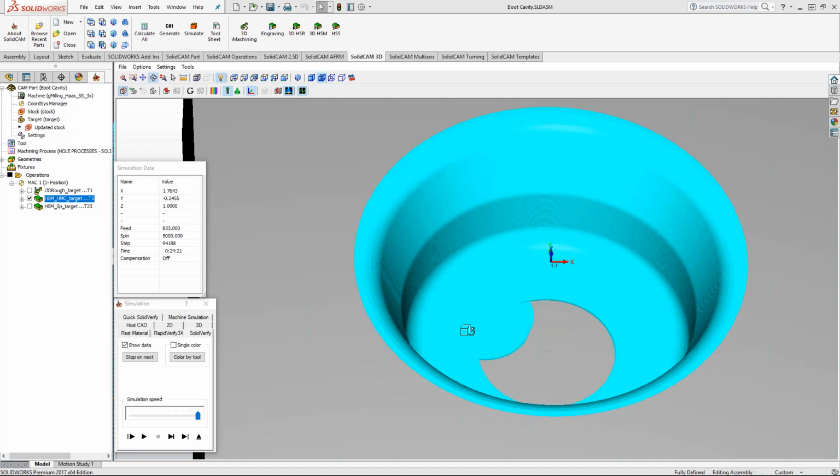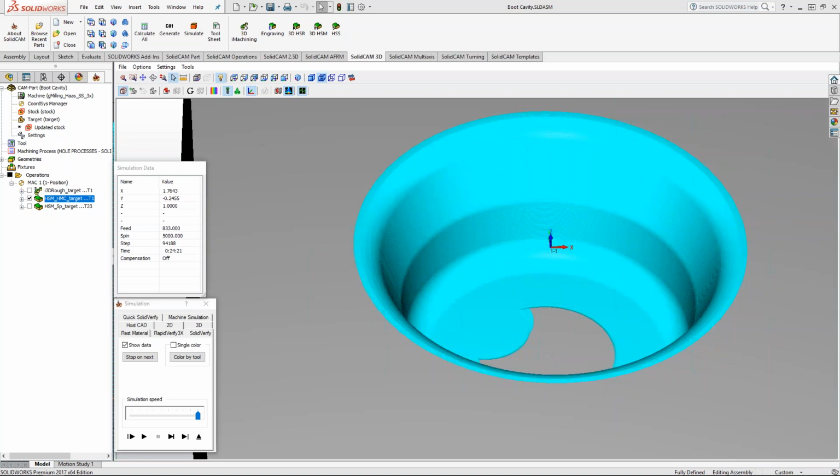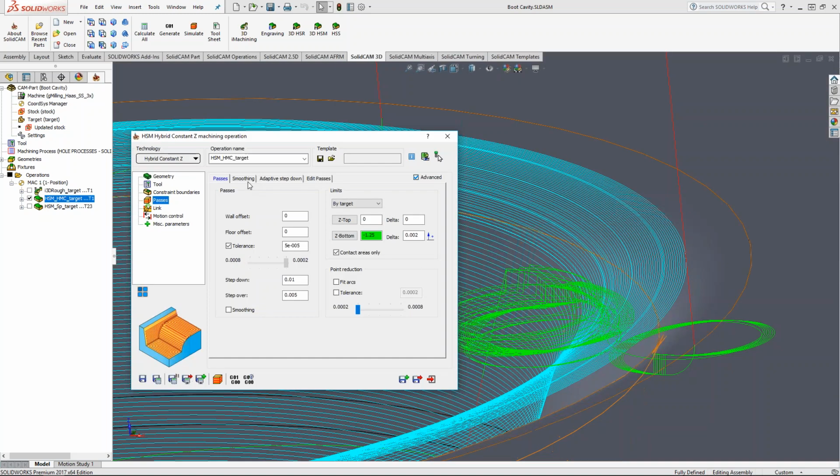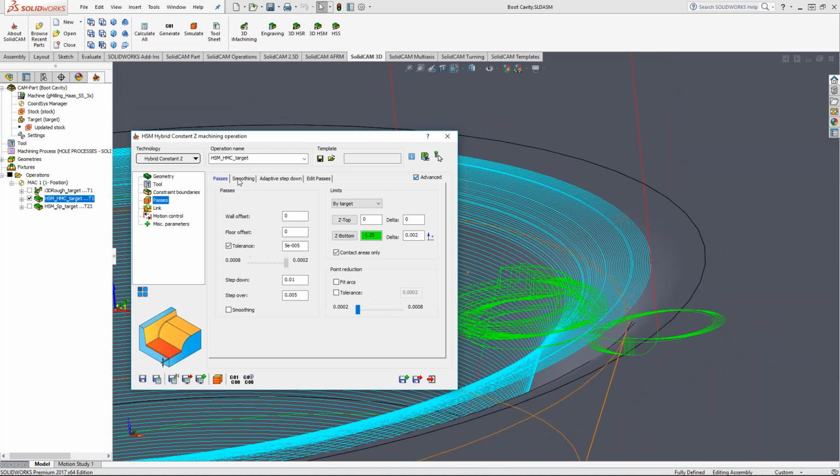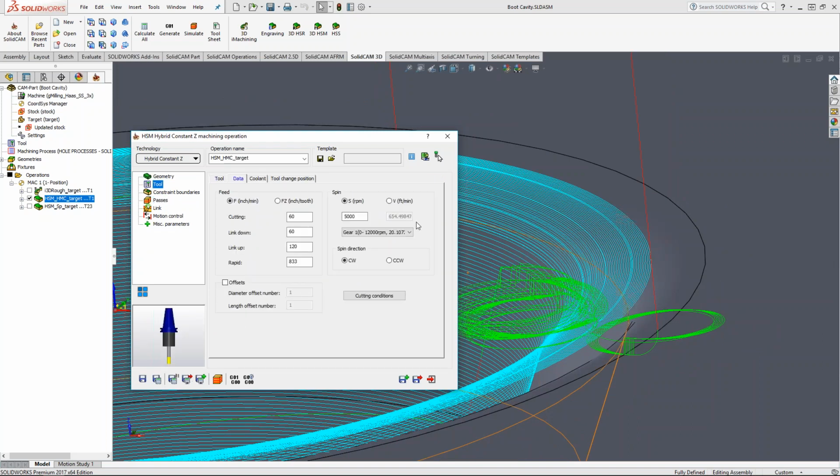All right, so Ronnie's asking, that seems double the published data. How'd you come up with these speeds, and what about inches per tooth? Okay. Rule of thumb that I've found over the years, let's go back here to the tool. If you'll look, I'm running about 650 surface feet.